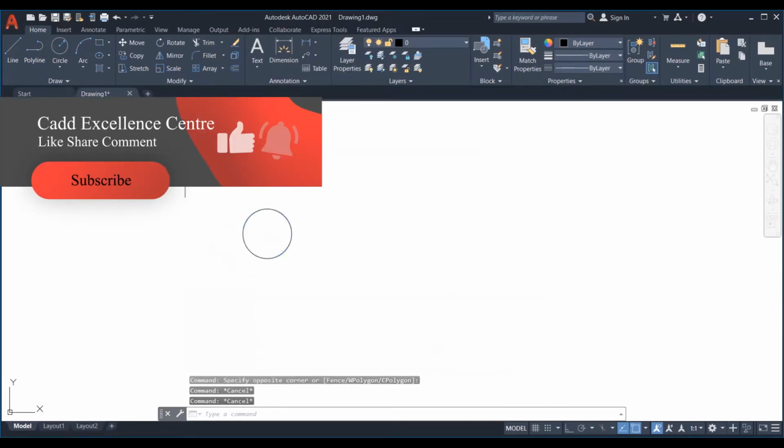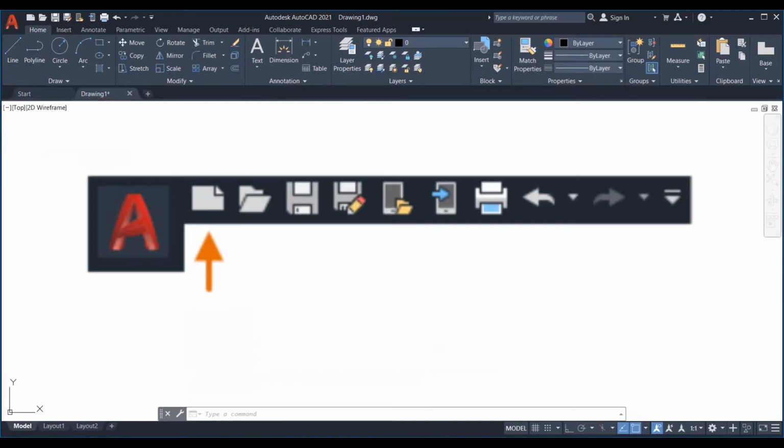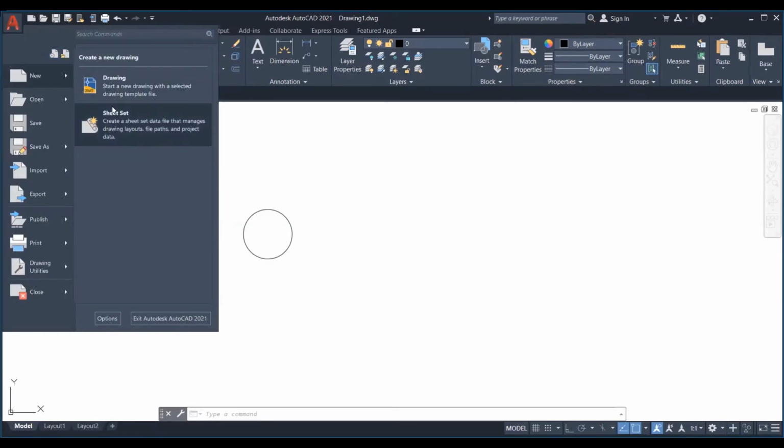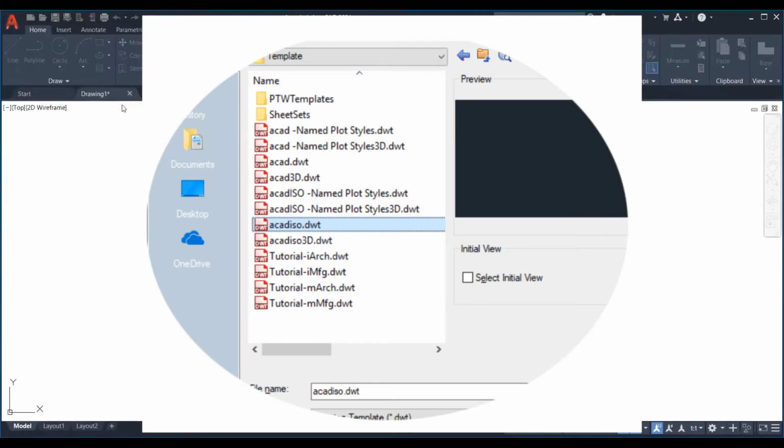New drawings. You can easily conform to industry or company standards by specifying settings for text, dimensions, linetypes, and several other features. All these settings can be saved in a drawing template file. Click New to choose from several drawing template files. For imperial drawings that assume your units are inches, use Acad.dwt or Acadlt.dwt. For metric units that assume your units are millimeters, use Acadiso.dwt or Acadltiso.dwt.